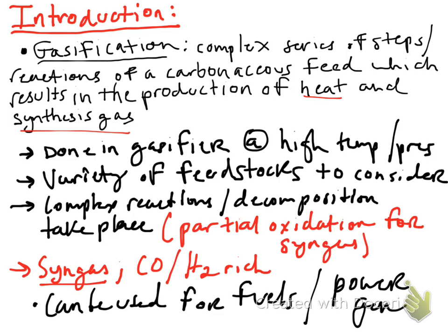You can actually take synthesis gas and burn it in a gas turbine after you've cleaned it up and you've done something called water gas shift, where you've balanced the ratio of CO to H2. And so yeah, there's a lot of different uses for gasification products. Of course, heat from the gasifier can also be recovered downstream. The syngas coming out of this gasifier is extremely hot, and so when you quench it, you can actually recover more heat. And we'll talk about that in a little more detail later on.